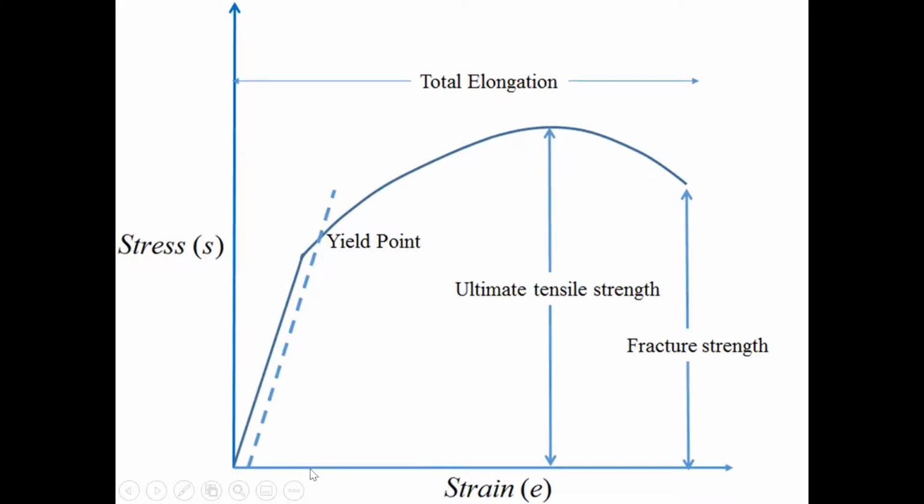So the elongation is along here. So strain is the same thing as elongation. We're stretching the sample because it's a tensile test. So we start here and we move along this way. So let's say this point here where it breaks is 10% extension of the original length. So if you had 100 millimeters, then we've increased it by 10 millimeters, 10%. Here we have the force per square meter. In other words, the stress. The stress is force per unit area. Hopefully you already know that.